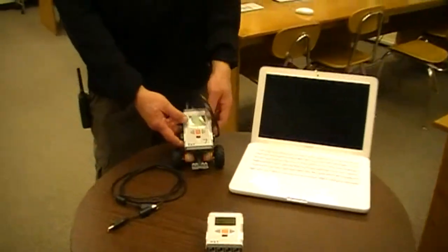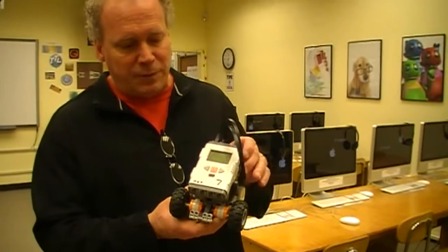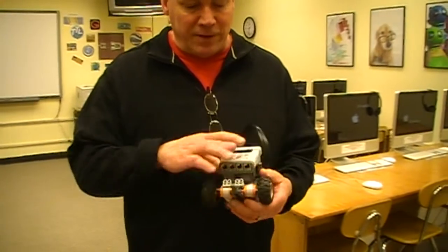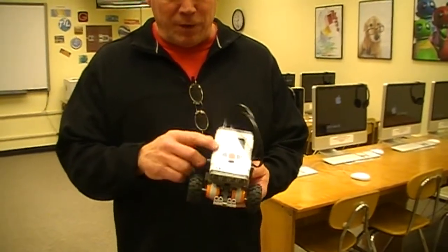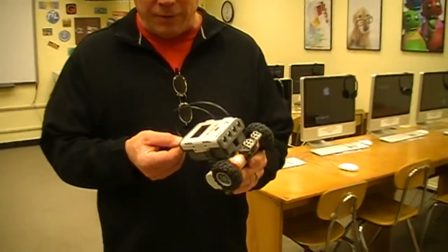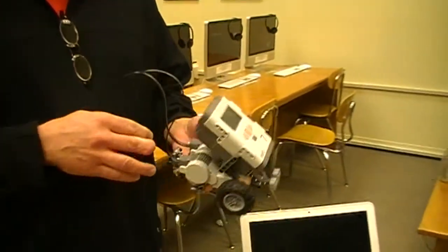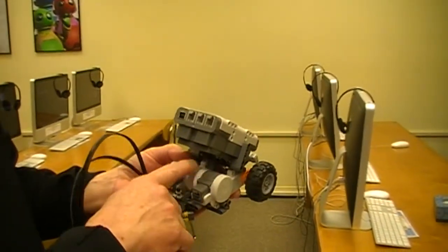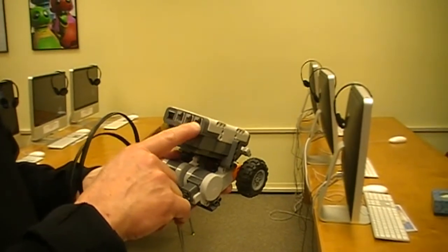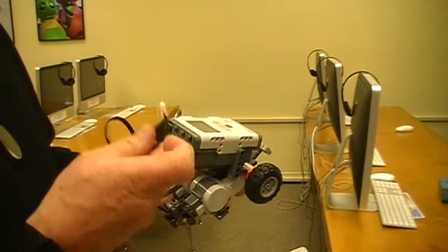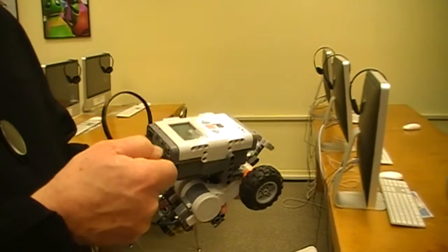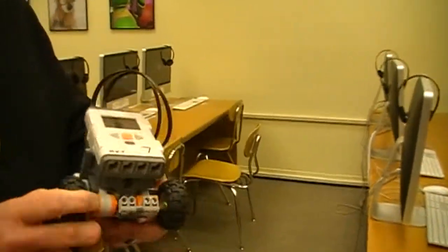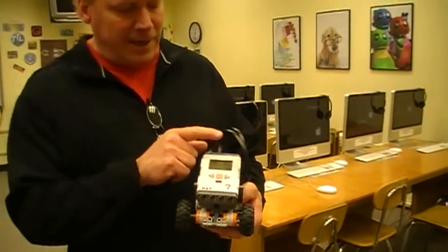When you put it all together, it looks like this. Okay? The difference between this and that is we now have two motors. These are your motors that drive your wheels. Now, in order for the brick to talk to the motors, you have to connect them using these wires. If you look at the top, you've got three ports, A, B, and C. So these two motors are going to be connected to any one of these three ports. Typically, it is going to be A and B. And that is going to be important once we start programming. That will be the second part of this video. But you just need to know that those ports are A, B, and C.